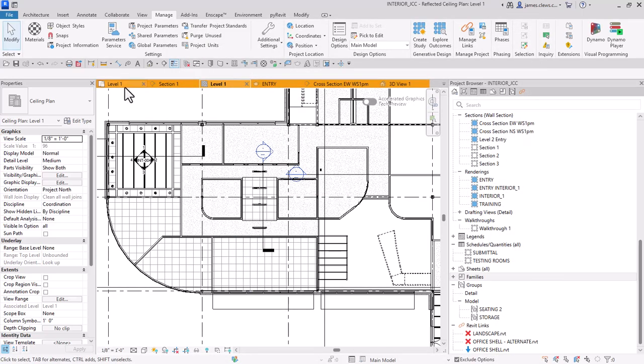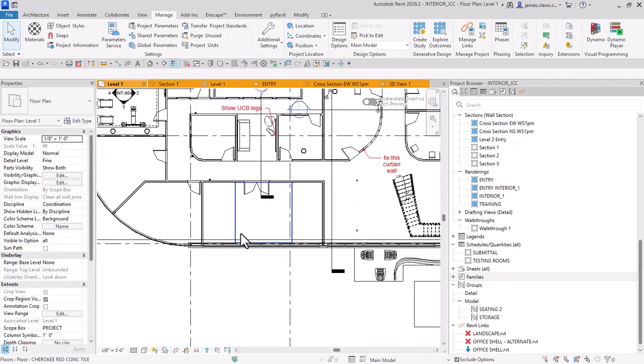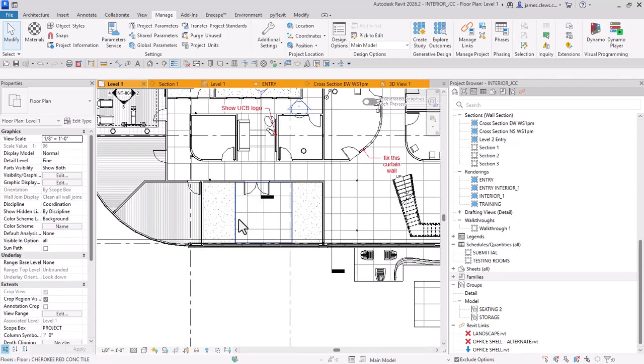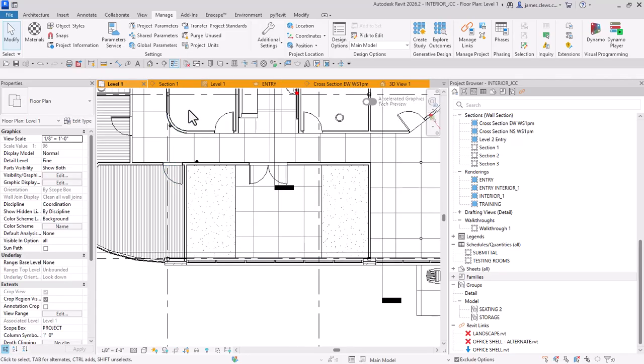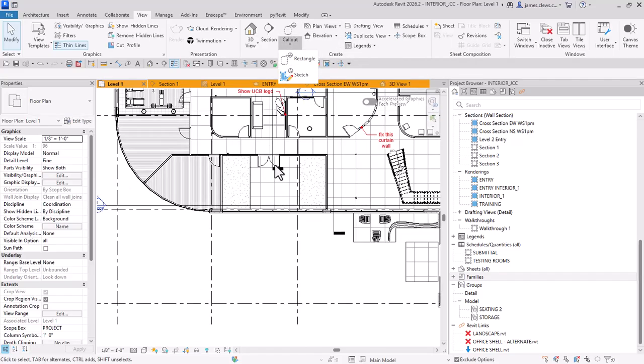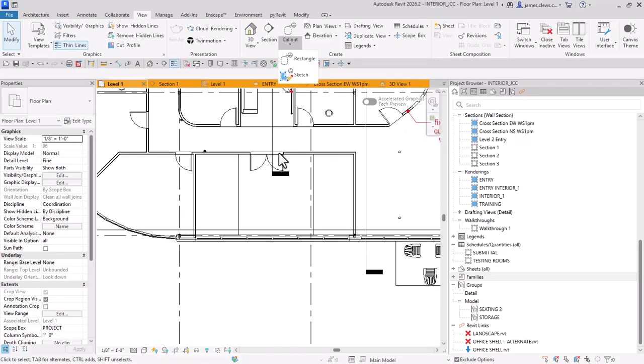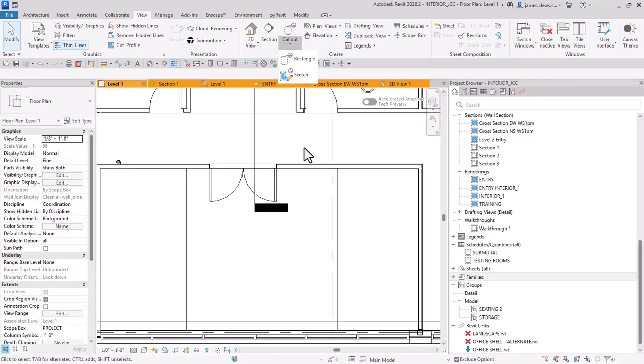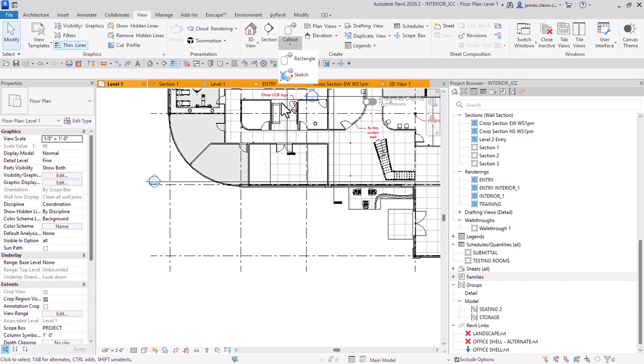And I want a blown up area of it. It would be the option to go to the view and use this callout to create a shape that you want to have at a different scale. You could also use, if it's a rectangular thing, just a scope box, but for example here, let me do one that is a